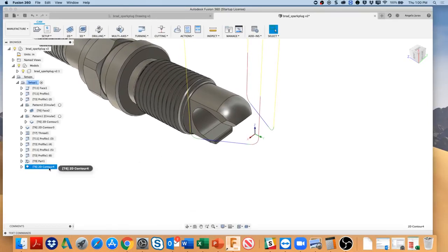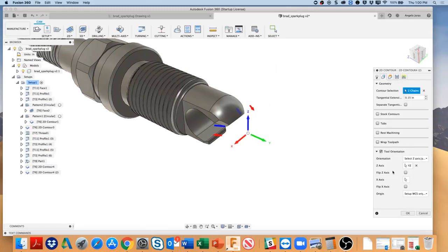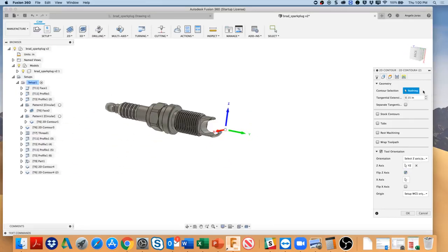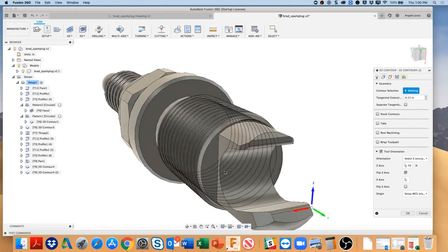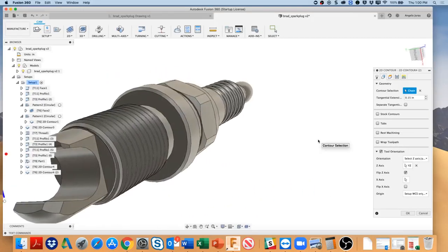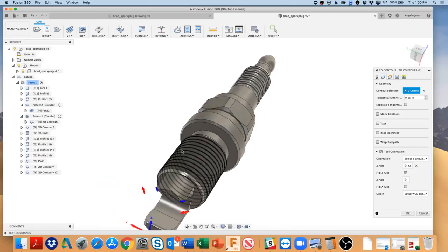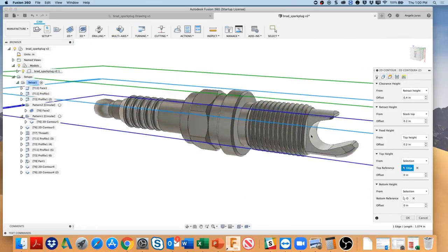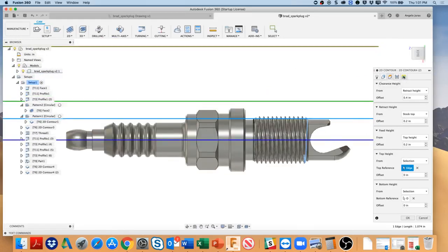Now I need to hit these chamfers on the bottom. I will just take that and I will duplicate it. And I will edit that. So the plane is the same, but check this out. I can just flip the Z so it's now the other orientation. I'm going to delete those chains and just come into, so I need this guy. Again, I'll hit Option and I'll get that contour, and again Option and that contour. I'll verify that it's on the right side, and the point it was going to on the heights was, remember, I picked that center point, and it's going to that. That's fine. And we'll hit OK.